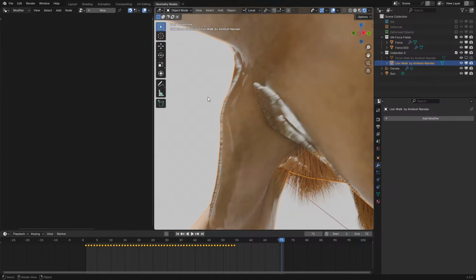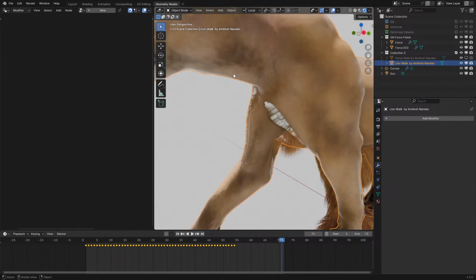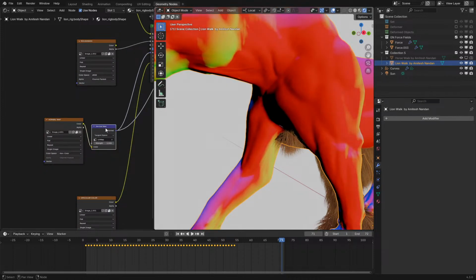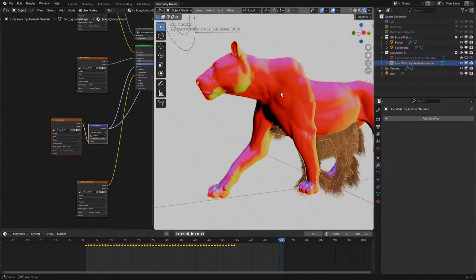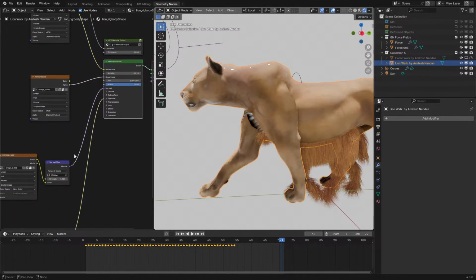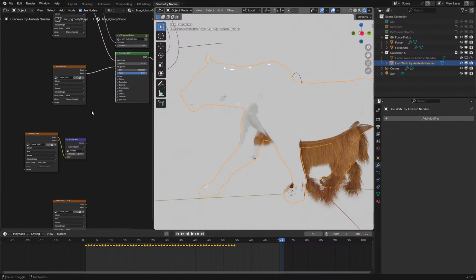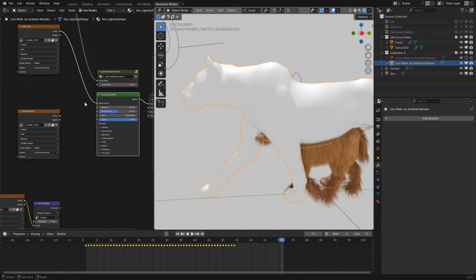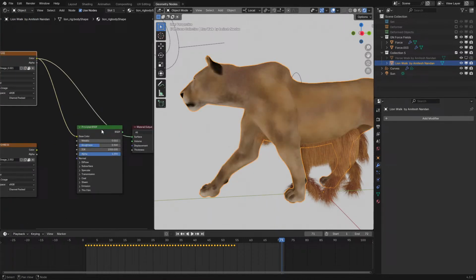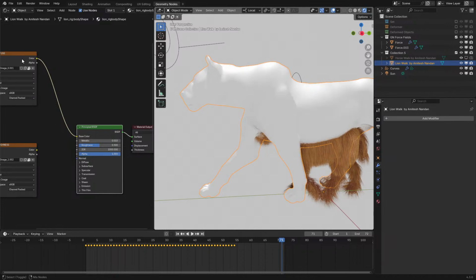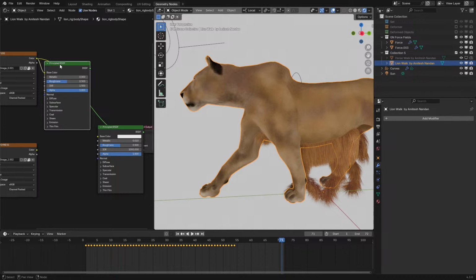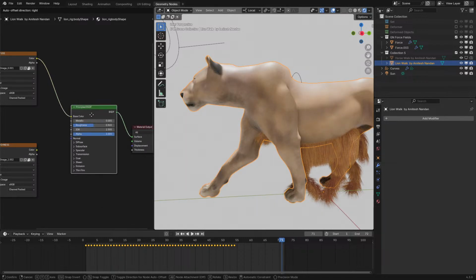This means that the normals, I think this only happens when the normals are severely inverted. Let's check the shader. Oh, yeah, there's a normal map. Oh wait, the other one didn't really have a normal map, did it? And then if we disable this, it just adds in a bit more definition, which we don't need. So we can eliminate this and this. Specular, we don't need the alpha. And only use the color, which, why is the color not going through? Well, let's just add in a new principled node and then call it from there. There we go, that's a bit better.